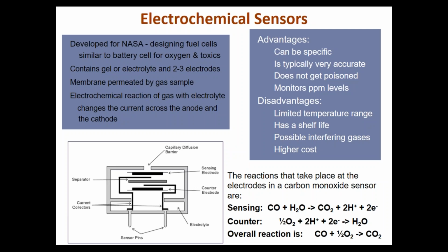The one exception is an oxygen electrochemical cell. Oxygen we're all familiar with in terms of 21%, or 20.9% oxygen in air at sea level, and therefore we talk about oxygen in percent by volume. A typical oxygen sensor will show you 0 to 25% by volume in a specific application. It's mostly used for oxygen deprivation or enrichment applications. So you want to know when you can go into a room that has enough oxygen for you to breathe.